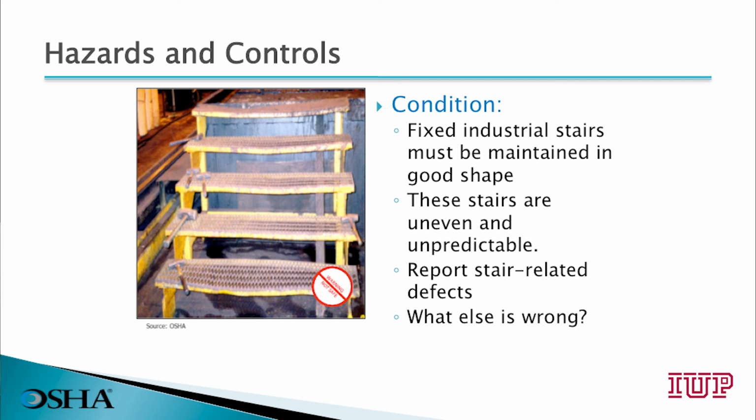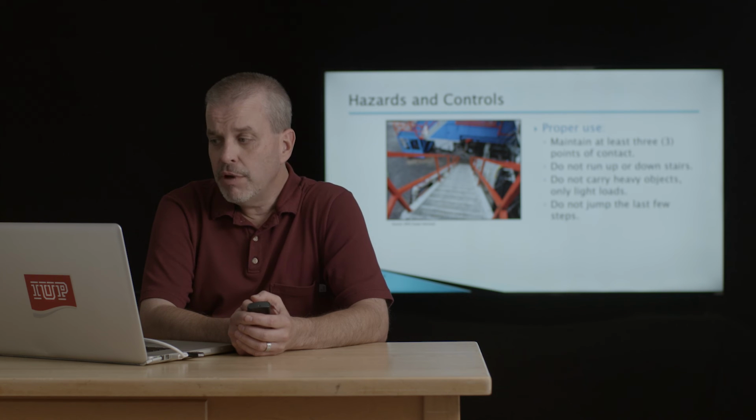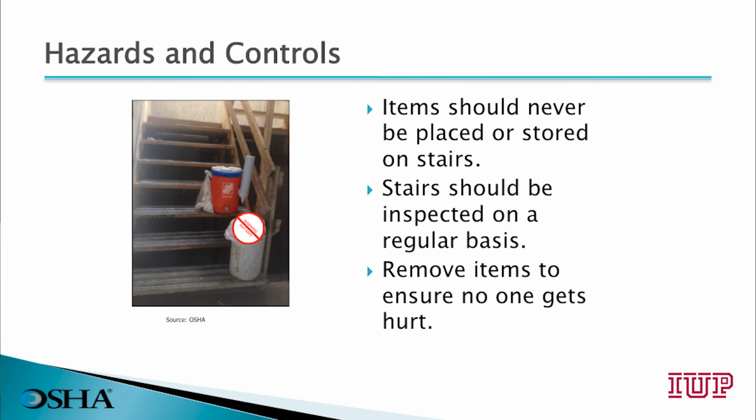What else is wrong with this photograph? Here we have more than 4 risers, which means we should have handrails on both sides. When climbing or descending stairs, make sure you maintain at least 3 points of contact. Never run up or down the stairs. Never carry heavy objects, only light loads. And never jump the last few steps. Items should never be stored or placed on a stairwell. Stairs should be inspected on a regular basis, and remove items to ensure that no one gets hurt.